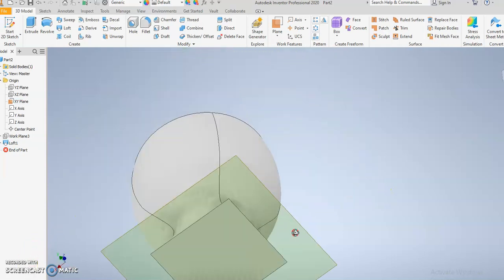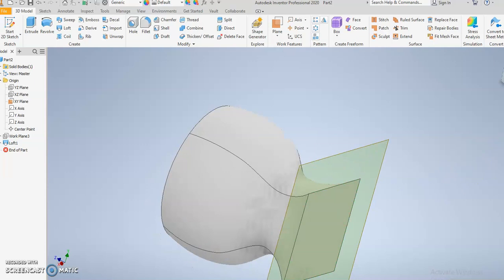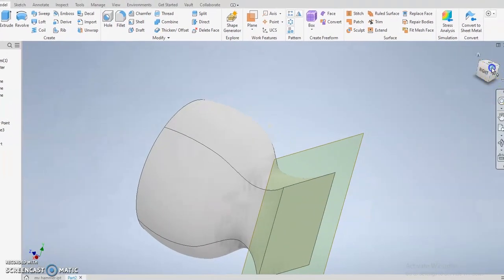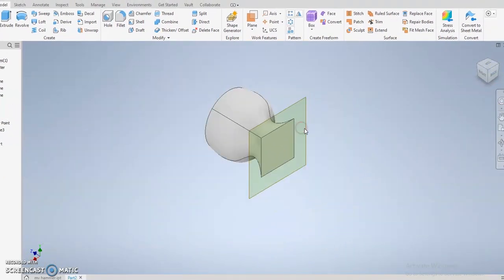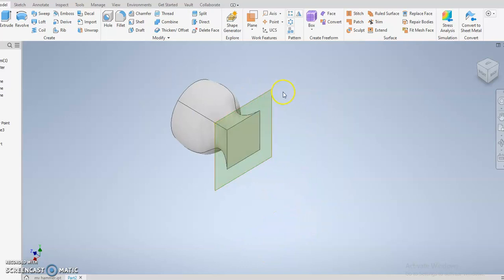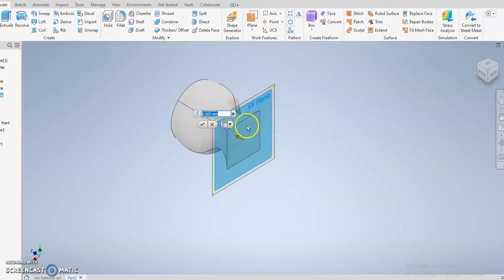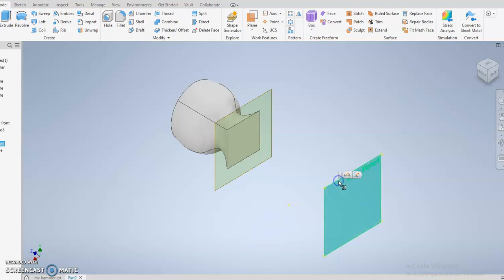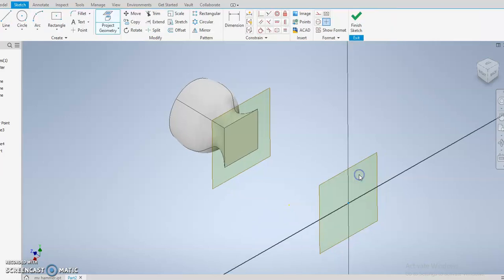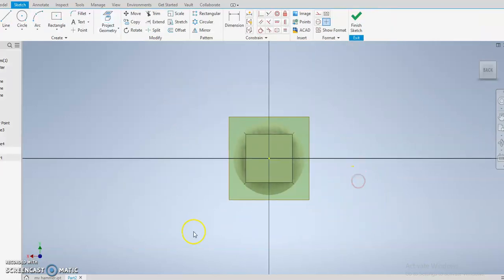All right, next plane here, I'm going to just rotate this so it's on a nice little isometric plane. And we have to do another offset plane here. So I'm going to choose my down arrow, go offset plane, click this. Now I have to go backwards, so you need a negative number. So minus 200 is a number that I'm searching for. Okay?